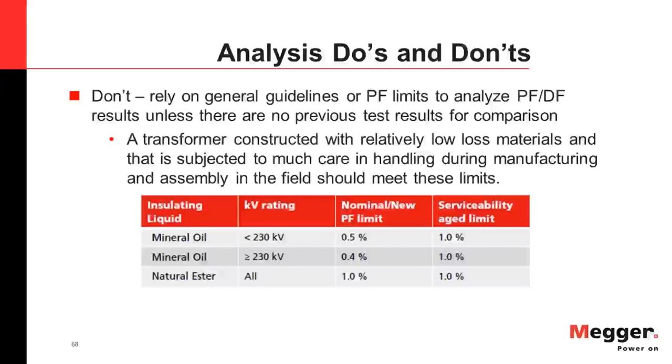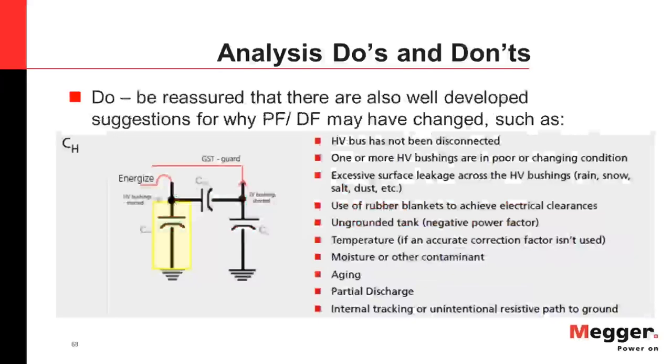Rather, power factor and capacitance values must be compared to previous measurements. And then finally, do be reassured that there are also well-developed suggestions for why power factor may have changed from previous results, such as shown in the table on this slide. And these also come directly from Megger's dissipation factor, power factor, and capacitance TLM bulletin.